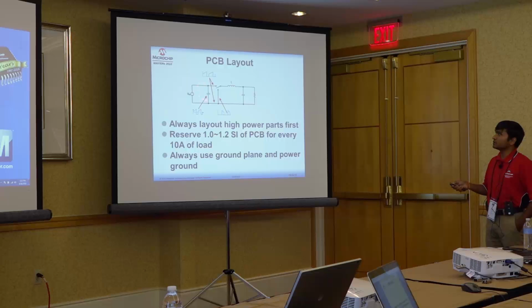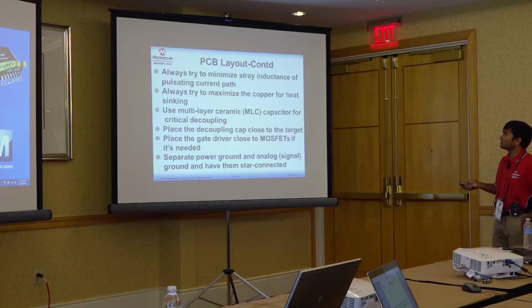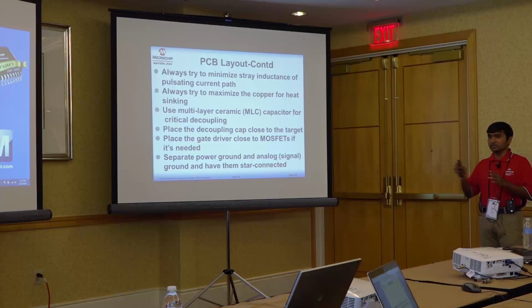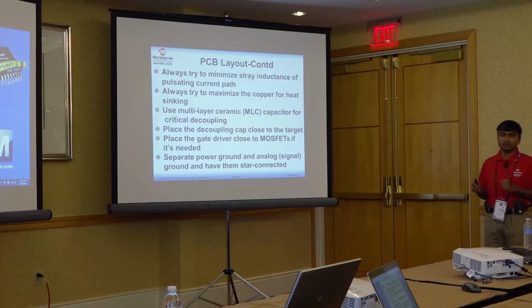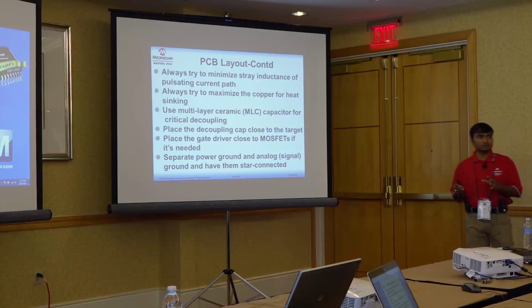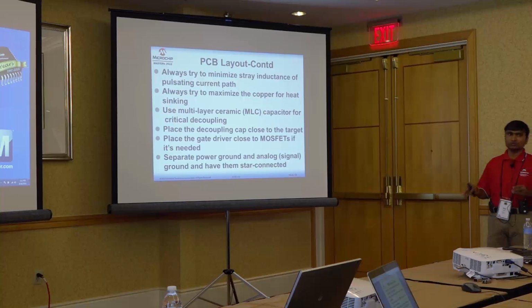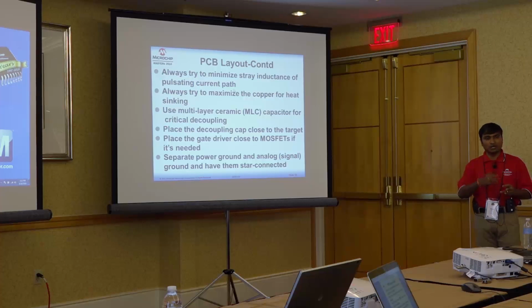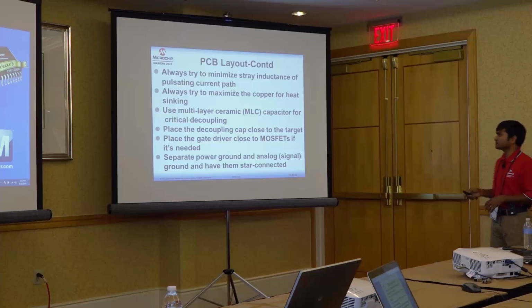So, provide good bypass capacitors at the input as well as the output, and always route the signal traces away from the high current switching nodes, especially because the COT needs the ripple coming from the switch node. Make sure that they are routed away from the switch node, and that they are not going underneath the inductor or anything like that.